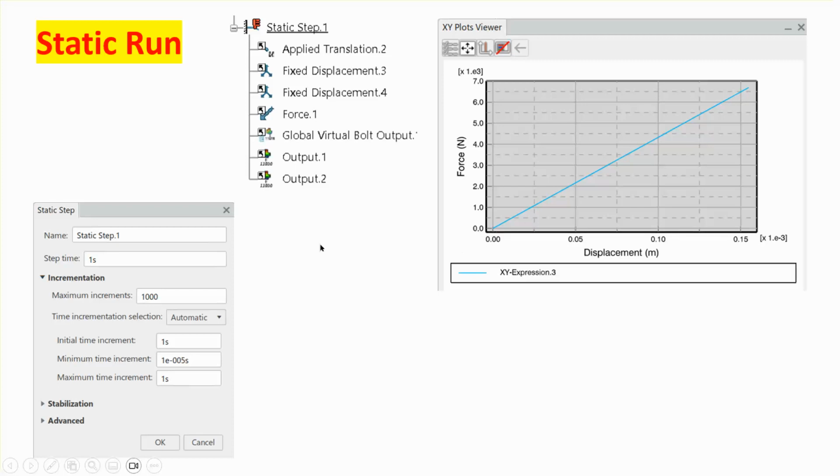You'll notice that when you do static analysis, or at least that was my experience, you get a straight line. Now things go nuts when it reaches roughly 0.15 millimeter, because there is going to be global buckling here. So I wanted to push it by 0.5, but it doesn't, because the convergence actually stops.